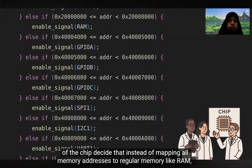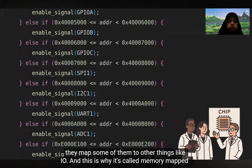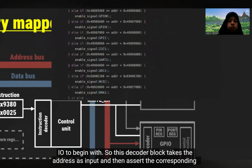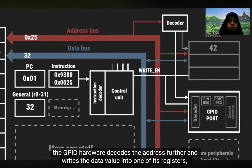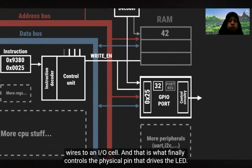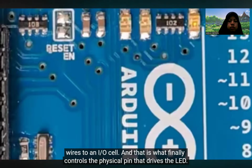This is where the designers of the chip decided, instead of mapping all memory addresses to regular memory like RAM, they map some of them to other things like I/O, and this is why it's called memory mapped I/O to begin with. So this decoder block takes the address as input and then asserts the corresponding enable signal. In this example, it's going to enable the GPIO hardware, and once enabled, the GPIO hardware decodes the address further and writes the data value into one of its registers, which is in turn wired to some additional control circuitry that further wires to an I/O cell, and that is what finally controls the physical pin that drives the LED.